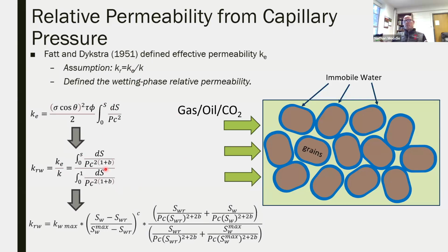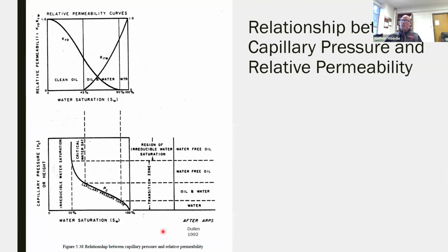And so from this basic understanding of how you can calculate relative permeability, I just discretized this formula, because we're dealing with discrete data, and so we need a way to calculate discrete time steps or discrete pressure steps. And so just using a triangular rule, I took the integral and turned it into this discrete formula. And this forms really the basis of the method for deriving relative permeability, here, in this case, water, from these capillary pressure versus saturation measurements.